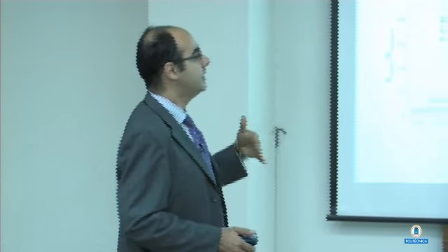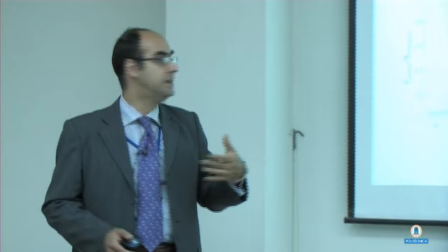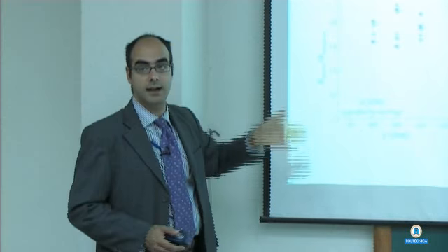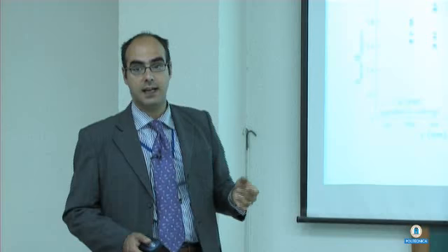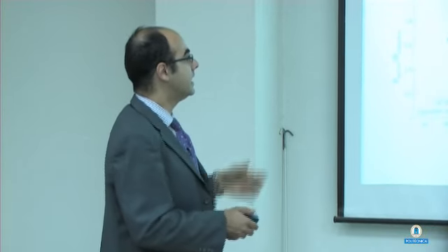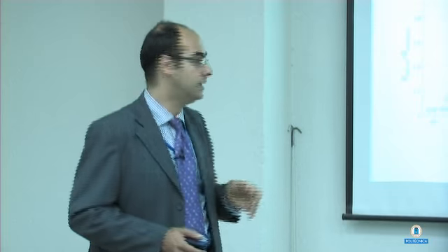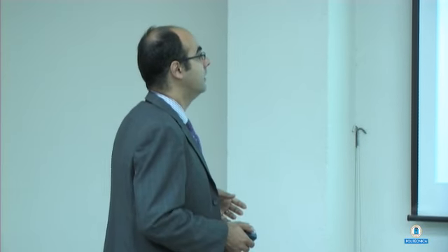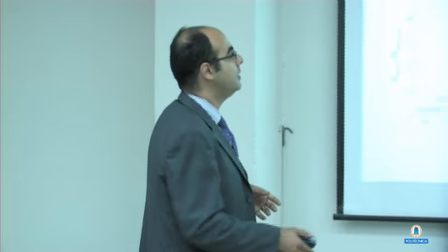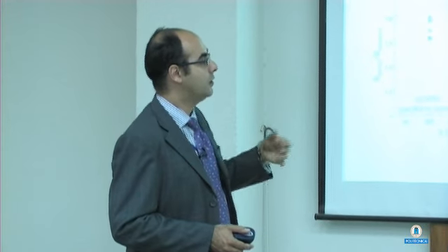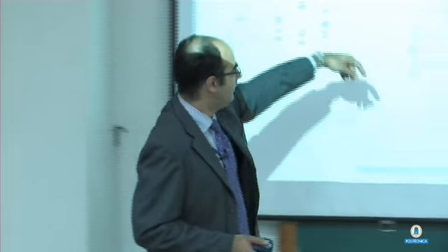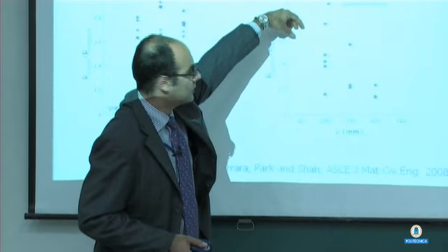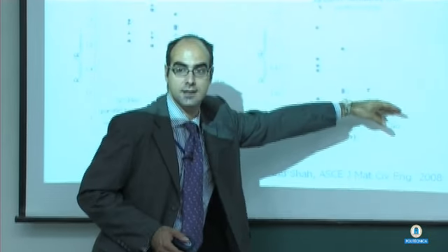And this is the comparison for the same slab. These are the measures taken parallel to the casting, and on the other side you have the results of the measures taken transverse to the casting. So you can see that there is a certain difference, and so the fibers tend preferentially to align along the direction of the flow. Here you can see when we use a very fluid concrete which is prone to consolidation, have in mind that the concrete was cast from here and flowed along this direction.